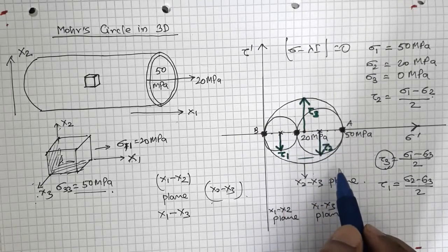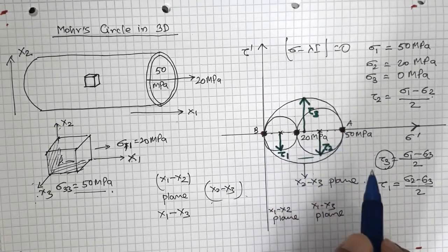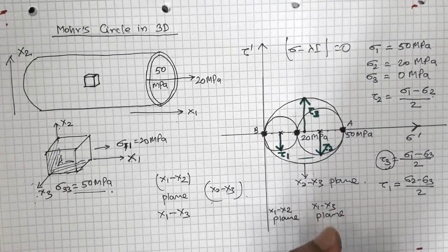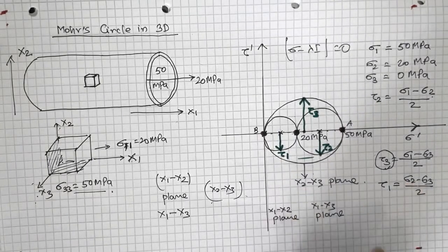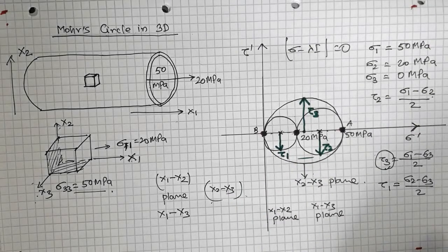If you can really draw the diagram, then you know the direction of the shear stress and the angle, if you want to reach a certain stress tensor value. So all that information can be obtained very easily from this diagram. Okay, so this is a very handy diagram of the Mohr circle in 3D. So now we have learned how to draw the Mohr circle in 3 dimensions and in 2 dimensions.